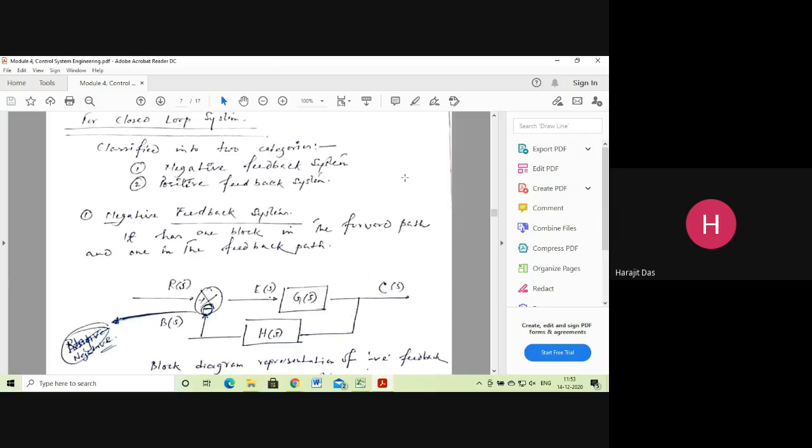How much do you need to add to the system again, at the comparator? It is plus 2 degrees, isn't it? So this will be a positive feedback system. If you are getting 25 degrees instead of 20 degrees, you need to subtract, minus 5 degrees, in the controller, isn't it? The sensors will be giving the signals back to the controller.